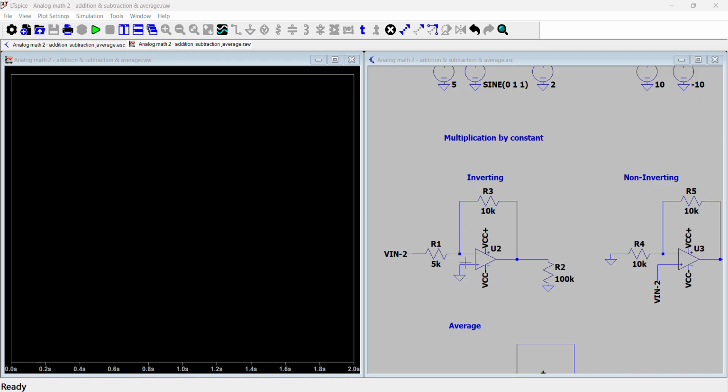So we use an op-amp, and the signal comes in through this path to the negative, to the inverted input through resistor R1, and then there's another resistor connected across, which forms the negative feedback from the output back to the negative inverted input. And the positive input is just grounded. And the output is just taken across the op-amp's output to ground.